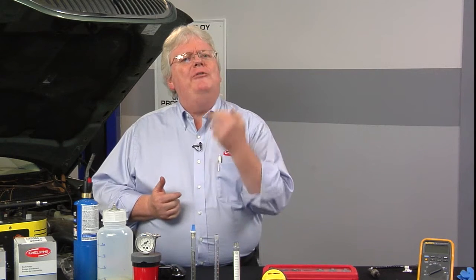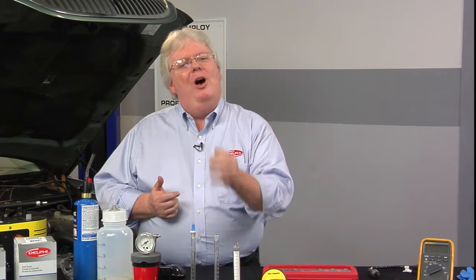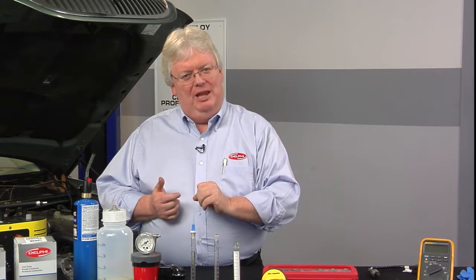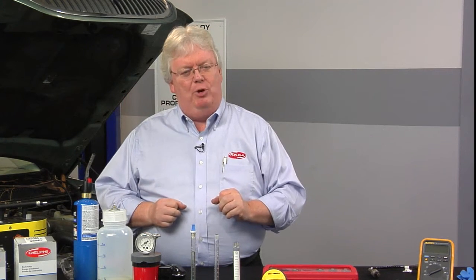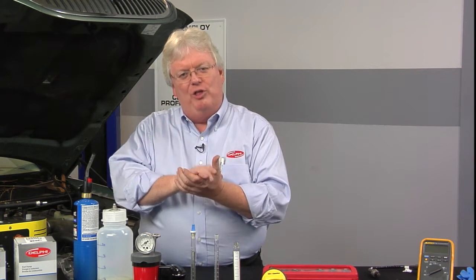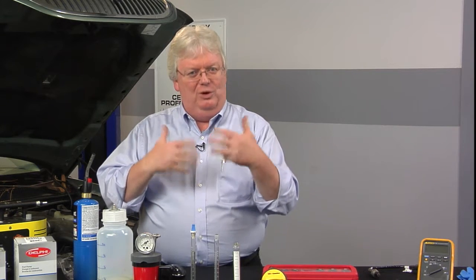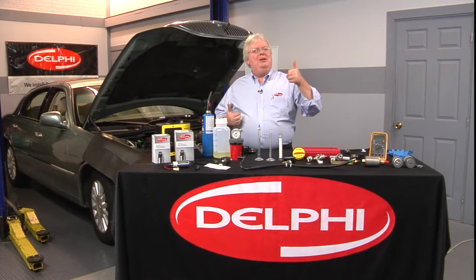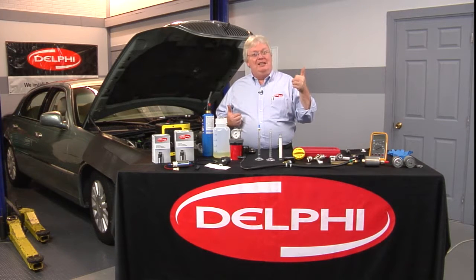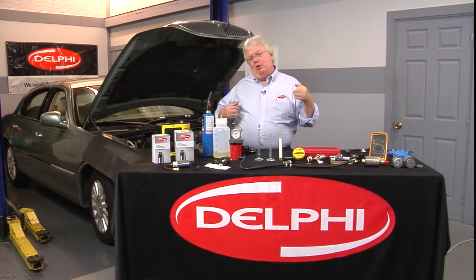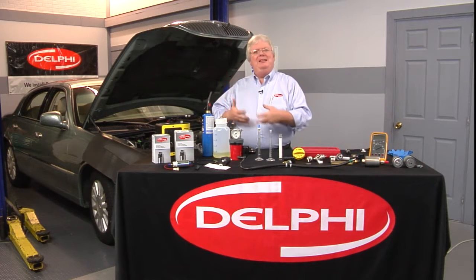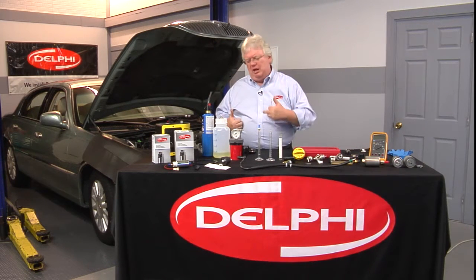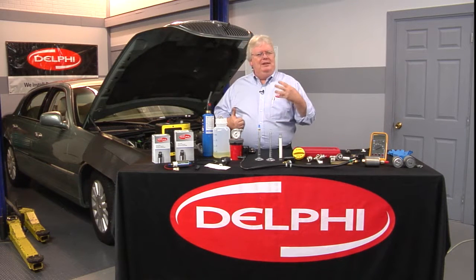And as you remember, if you're a tech who worked years ago on throttle body injection, like with GM Chevy V8s, for example, the gasket between the manifold and the throttle body was a notorious source of leakage, just a bad gasket. Well, the idle would go up because speed density systems sense less vacuum. Therefore, it adds more fuel to go with it, like there's a greater load. It makes the engine RPMs go up if you don't have throttle by wire. And now you have an excessive idle speed.